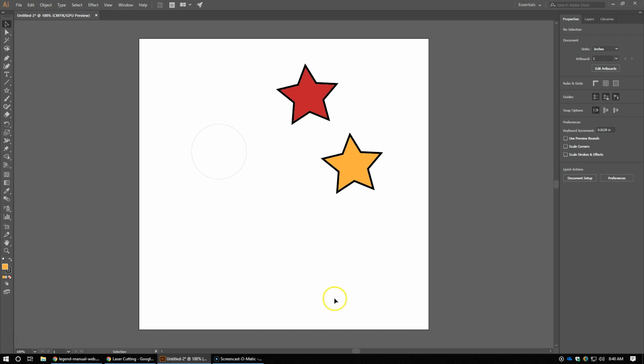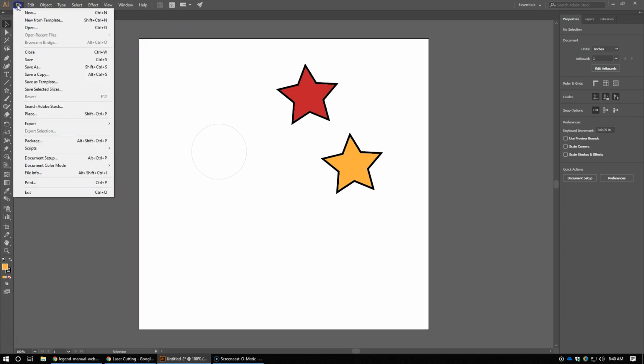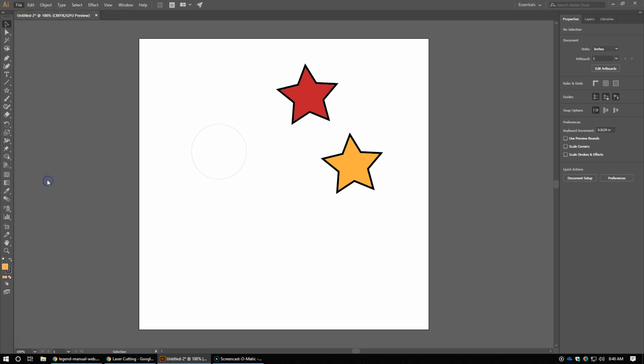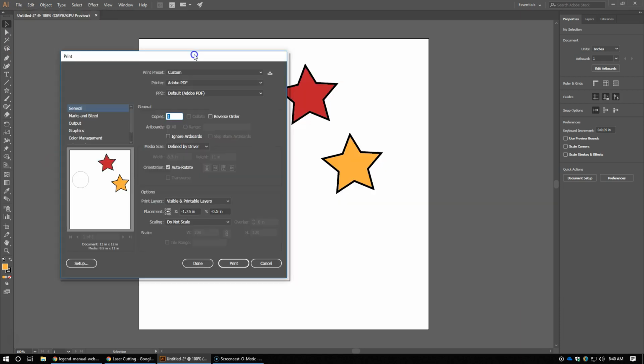Now, here are some additional steps. You have to be very precise with this. So let's say I okayed this. You're ready to print. We go File, Print. Now, printer. We have to select the proper printer. It's the Epilog Helix 24. So room 112, Epilog Helix 24. So I click that. Nothing here we have to change.